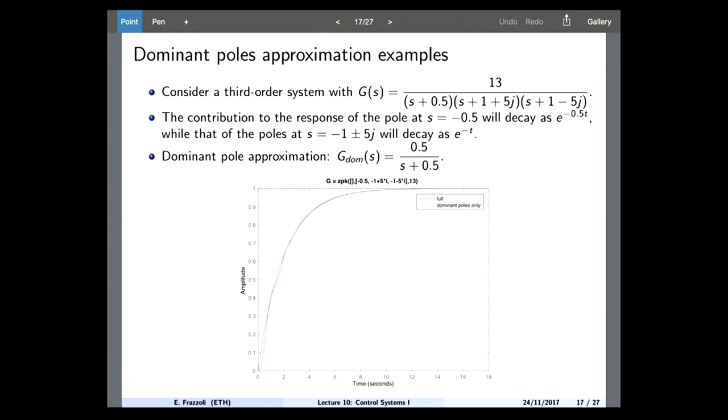Is there a reason why we can approximate that only for one of the poles and not use 2 of them? Is it just because the other one has the same behavior? So essentially what we said is that we approximate this with these 2, right? The complex conjugate, right? Actually, we approximate it with this one, because this one is the pole that is the furthest to the right, right?